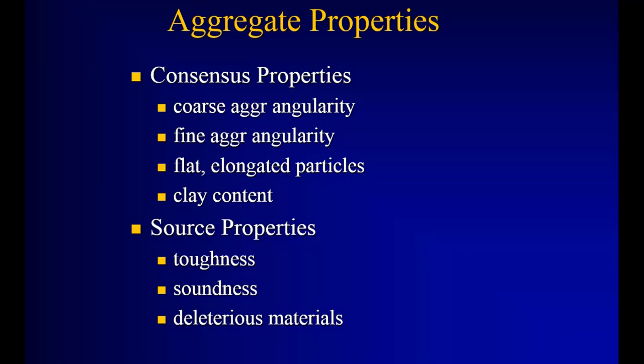What did we do before Superpave as far as trying to assess that material property, aggregate property? There were 2 ways basically. One, you restricted the amount of, quote, natural sands that you allowed into the aggregate blend. So lower traffic volume mixes, you would essentially have no limit on natural sand.